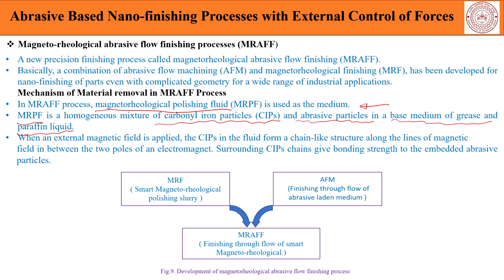The advantage of this process would be that when the actuation goes away, for example, the magnetic field is eliminated, you will suddenly see the change of state of viscosity back to normalcy. So, there is a relaxation effect which happens when there is no magnetic field, and so you can now define area-wise on the surface where you would like the apparent viscosity to go up and where you would not like it to go up, and in a way that is the basis of even customizing the material removal rates at various zones of interaction of the MR fluid with respect to the surface in question. So, that is the basic scheme of events here.